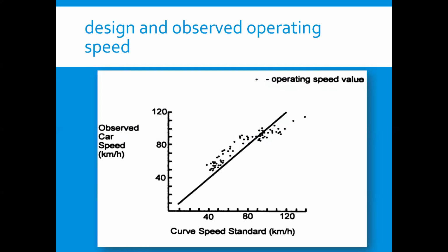These findings prompted a revision of the Australian design procedure for lower design speed roadways, noting that all of these studies have concentrated on high-speed rural roads. Similar studies have not been conducted on the major urban roads to determine if the same relationship exists between vehicles' operating speed and the horizontal curves. So, the geometric design of major urban roads based on design vehicle car should be based on operating speed 10 kilometers above the legal speed.